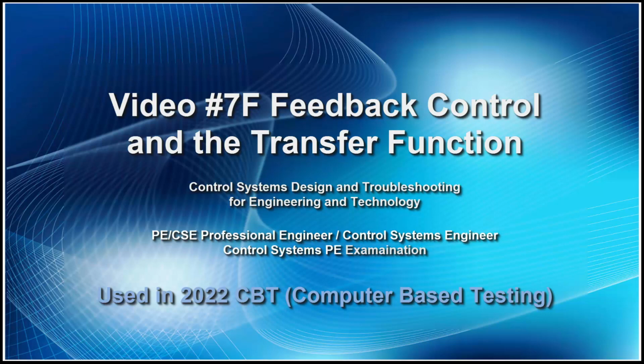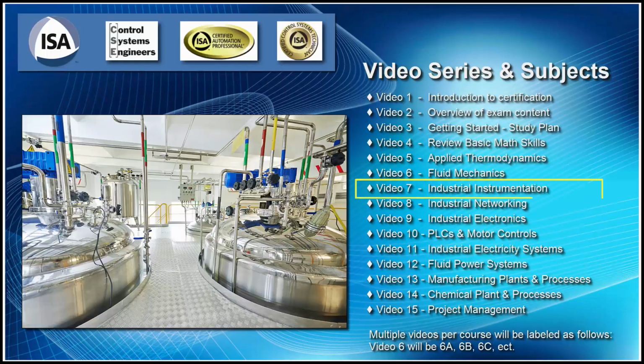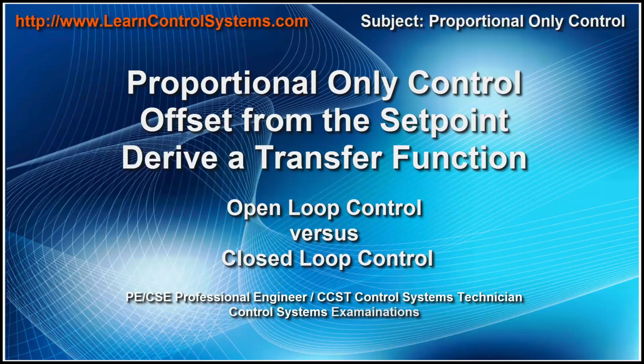Disturbances always exist. So let's get started, and we'll take a look at what a transfer function is, and a little bit about frequency response and filters that may be on the exam as well. In this section, we'll show that proportional only control just stops the upset. It doesn't bring the process variable back to set point. And we'll prove this with math.